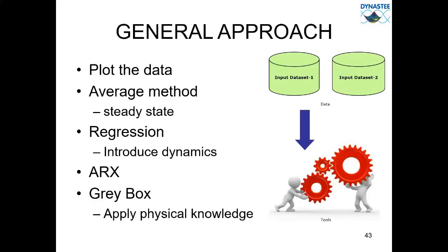Here we put it again: from data using the tools, plot the data, average method, so you get a rough idea of what it represents. By regression techniques, introduce some dynamics, use the ARX or ARMAX models, and maybe at the end you may decide to apply gray box models. That is exactly what we are trying to do with our presentations. We start from the not too complex situations, and we will end up by the last webinars with the application of CTSM, the application of the gray box models.